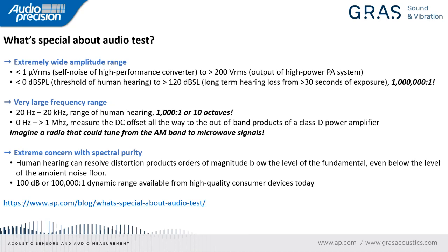And well, why can't we just make that measurement with, say, a handheld multimeter or an oscilloscope or some other kind of off-the-shelf, or I'll say common instrument? And well, the direct answer is you can. A multimeter will measure an AC voltage. A scope works just as well, but there are some unique characteristics about audio signals that lead us to want to use some specialized equipment.